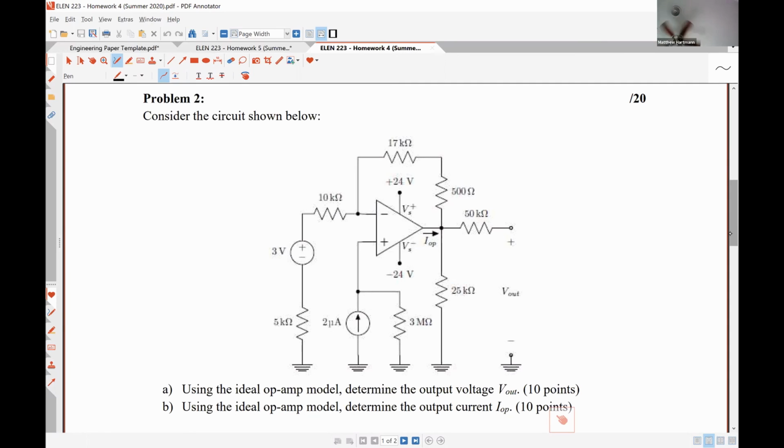All right. And you mentioned something in the most recent lecture that you can't do Kirchhoff's current law at the output node. Would that apply here, or is that not relevant to this? So you can't do Kirchhoff's current law at the output node. The reason I was saying that is because we don't have a relationship for the output current I_out.